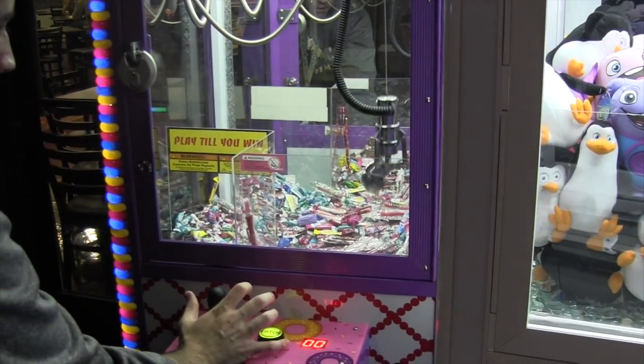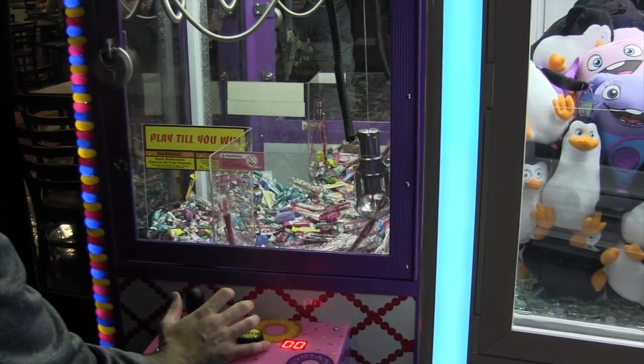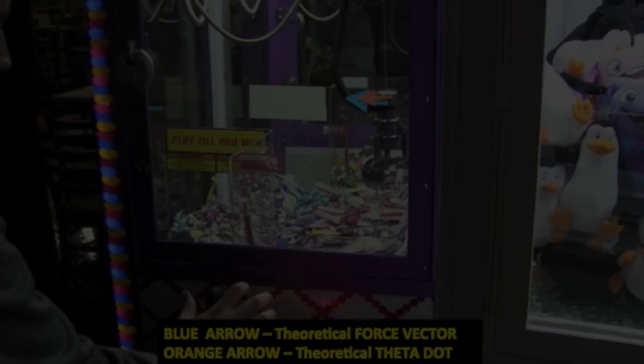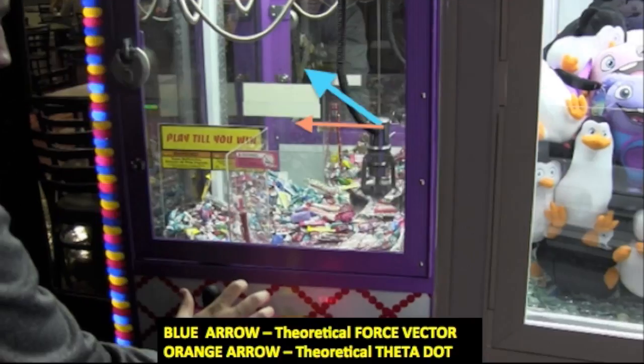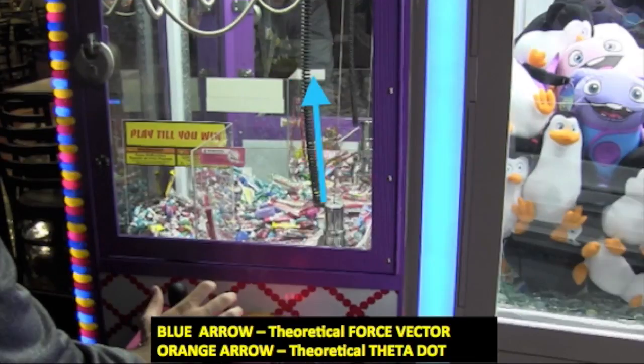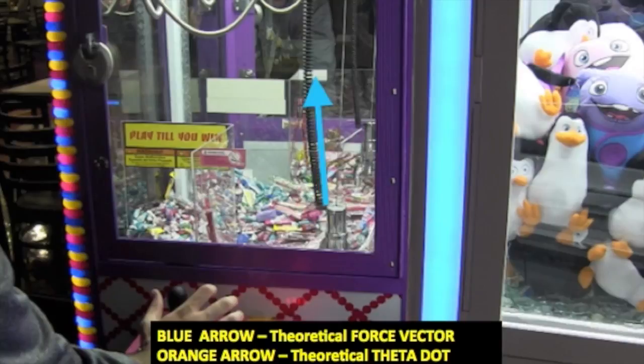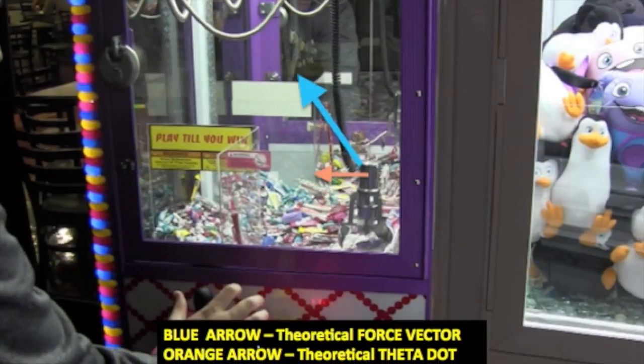With this claw, the dangling coil that supplies power causes the claw to rotate as it lowers. This becomes very difficult to describe since the three-dimensional force, the angular acceleration, and the distance x from the top of the machine are all changing simultaneously and depend upon the claw's frictional components and internals. If we define the claw's position when it is at the top of the machine as theta equals 0, we can infer that if there was nothing to stop its rotation, the claw would stabilize 180 degrees later on the side where the coil is connected to the machine.